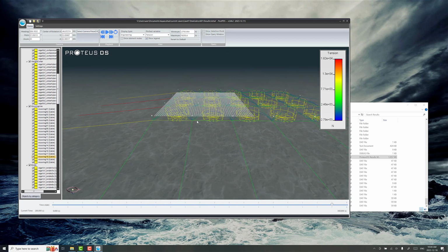There's more than one way to apply wave loads. A very standard process is to use a ramping up area wave, like a sinusoidal wave, and then a full wave amplitude to sort of get a maximum wave going through the whole system and see what the dynamic load is on top of that. And that's what we're going to show how to do in this tutorial.